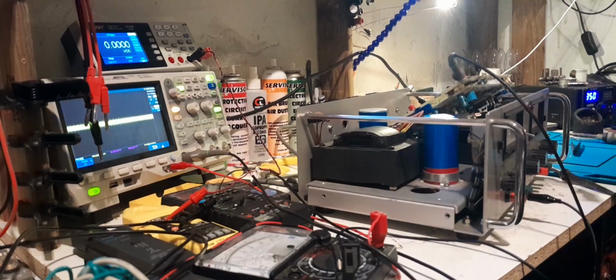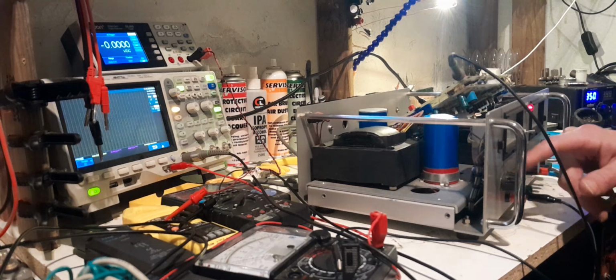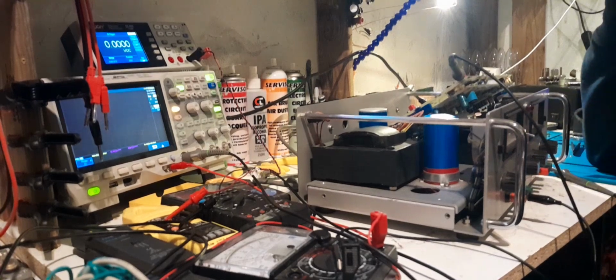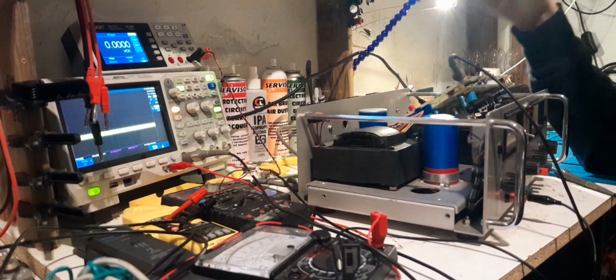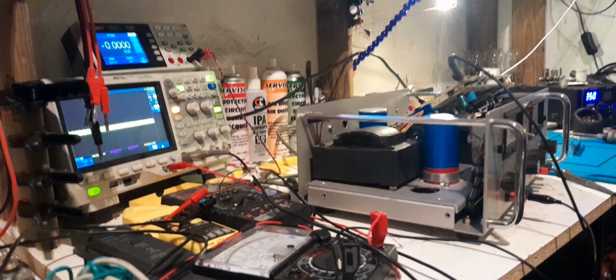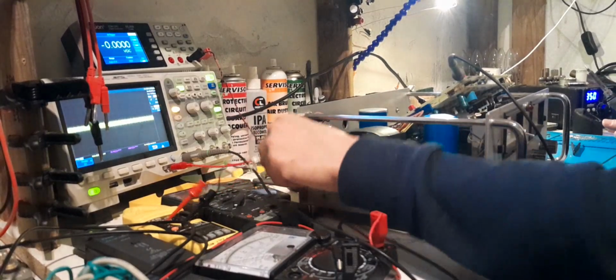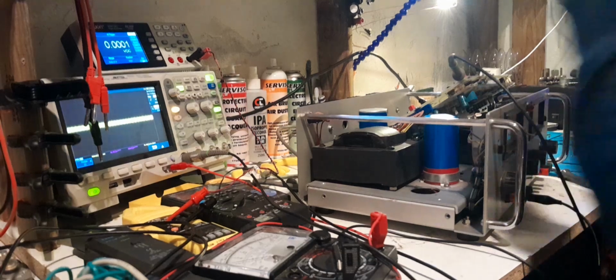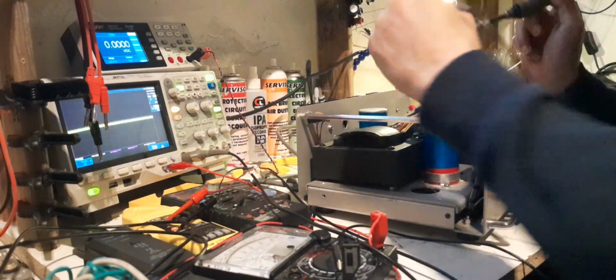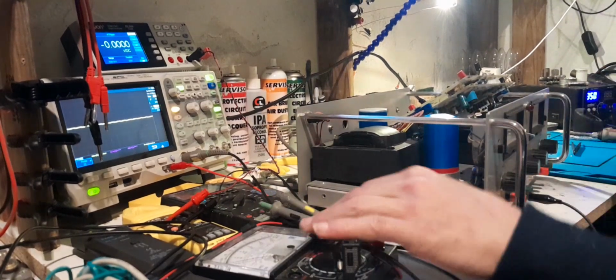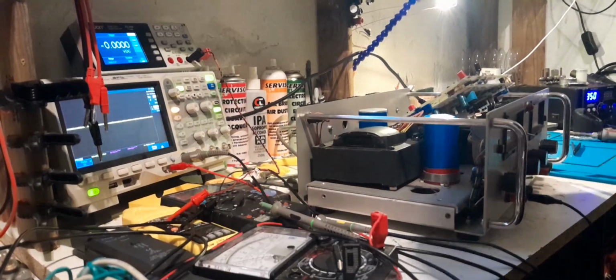Finally did it. Yeah, that's gone. That is not how that looks. Oh, that's gone. I'm going to have to change that op-amp. I just took the soldering iron to its output with the negative terminal reference to ground on the scope, and the power supply was still switched on. I can't believe I just did that. I'll be back in a moment. I've got to change my op-amp. Sorry about this.